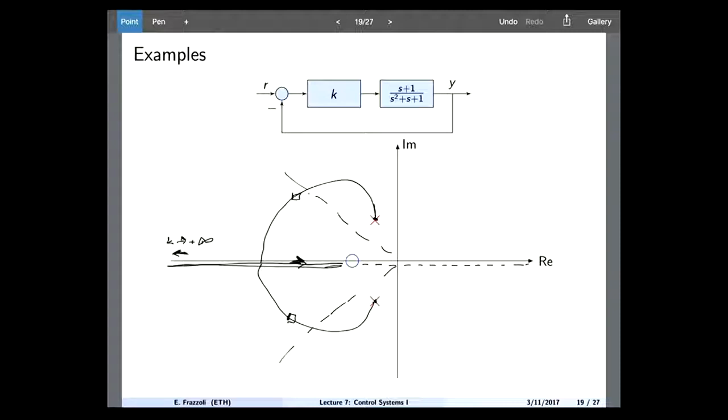The point of the root locus, for me, is not to give you detailed, precise answers. The point of the root locus is to see whether or not a certain design may actually work, okay? And in this case, you know that this is a system that I can stabilize and get to a nice response just by using proportional feedback, just using a feedback gain, okay? Again, the point of the root locus is to give you the 5-second answer to the question, what is the right control architecture for this system?